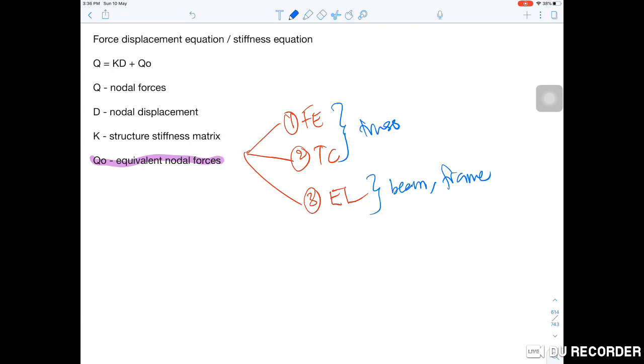In a beam, we have to distribute to 4 values, depending on the degrees of freedom. For a frame, since it has 3 degrees of freedom per node, we distribute the external load into 6 values using the formula. For fabrication error and temperature changes, remember that this is force, and the unit is kilonewton. And we have to distribute the value into 4 values.